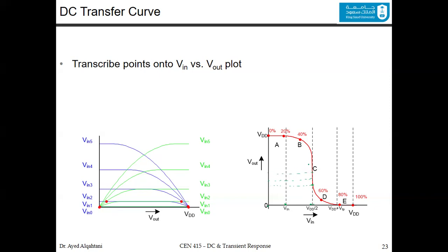So it's an unknown value, what we call a dangerous region, or we can say X, or don't care. And this is what we don't want. We don't want the input value to be VDD divided by 2. Even near this region, it's not that good.